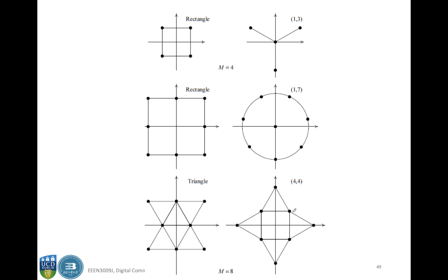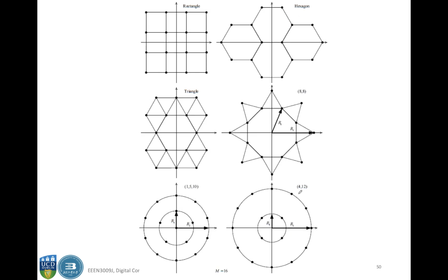Your signals are at these points, and depending on where they are in the signal space, they have a unique energy, or a unique amplitude and a unique angle or phase. Therefore the ith signal is defined by both a varying amplitude and a varying phase, and we can have a QAM like this.